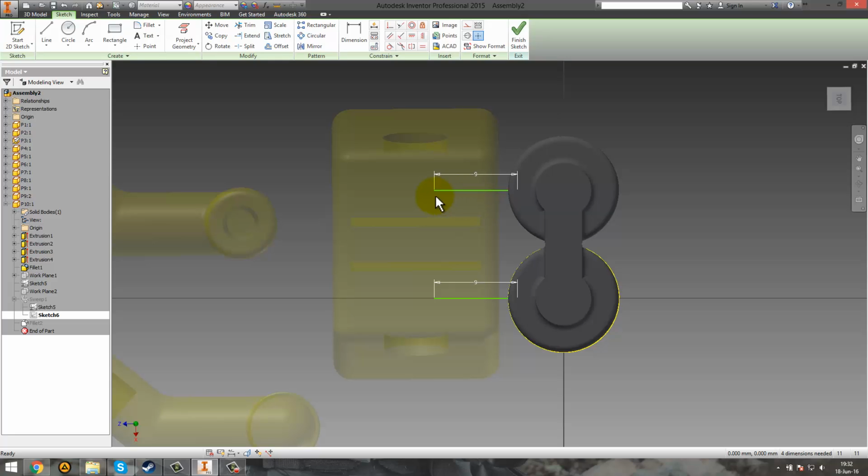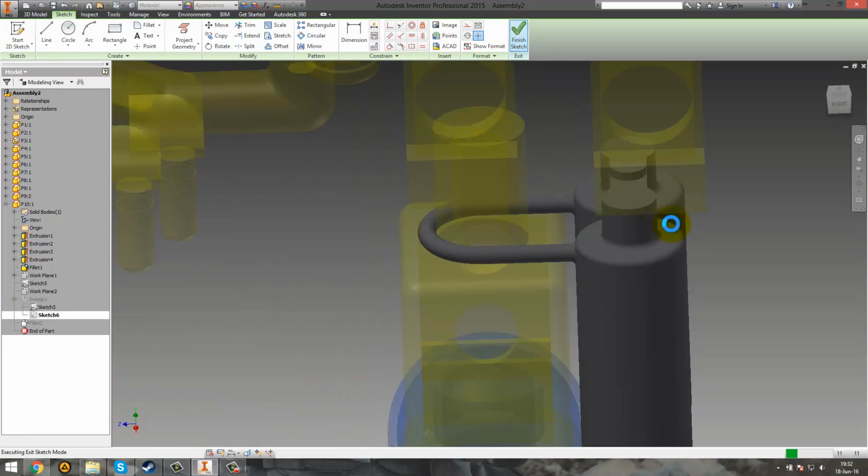And now in your drawing you should have this line. You just need 1 more millimeter, not 2 as before. So if you prolong it by 1 millimeter and then do the circle again. Okay, really easy. Snap in the center, trim. Okay, delete this one, exit.